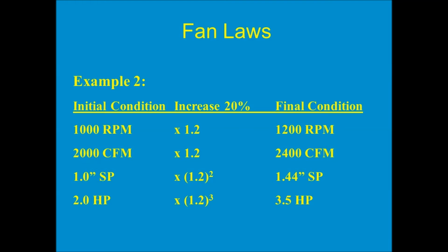And they don't make a 3.5 horsepower motor. The next size is 5 horsepower. So it's not just $50 for a new set of pulleys to speed up the fan. You need a whole new motor, and that's going to cost about $500. So the restaurant owner says to us, "Oh, you're kidding me. You mean I got to spend $500 for a brand new motor just to get 20% more CFM?"